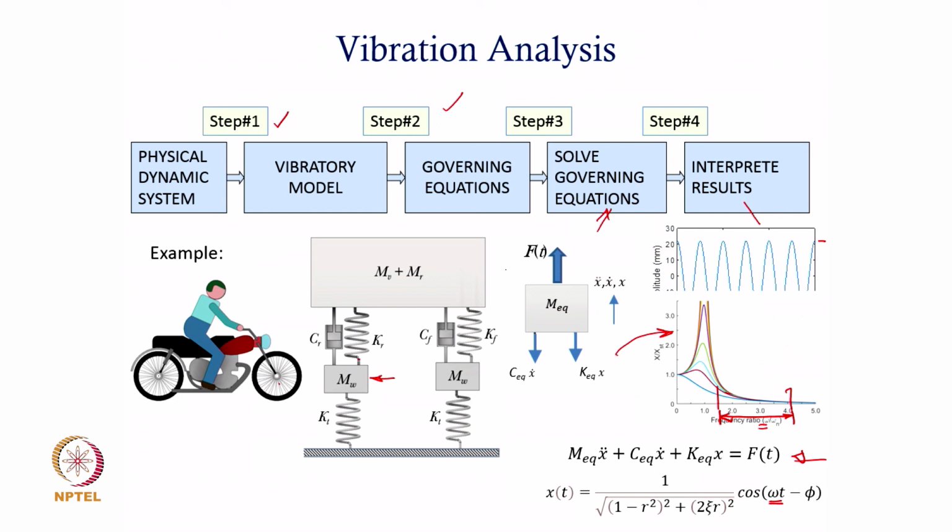So, this isolator or suspension element would be separating the wheel and the chassis, as also the dashpot, and I can then model the flexibility or compliance of the tire as another spring. I can model the tire itself as a spring element, which will capture the compliance that any tire that has been designed has, in the form of a spring here. So, a tire gets modeled like a spring, and the wheel is modeled like another independent mass, because the wheel can vibrate irrespective of the way the chassis is vibrating.